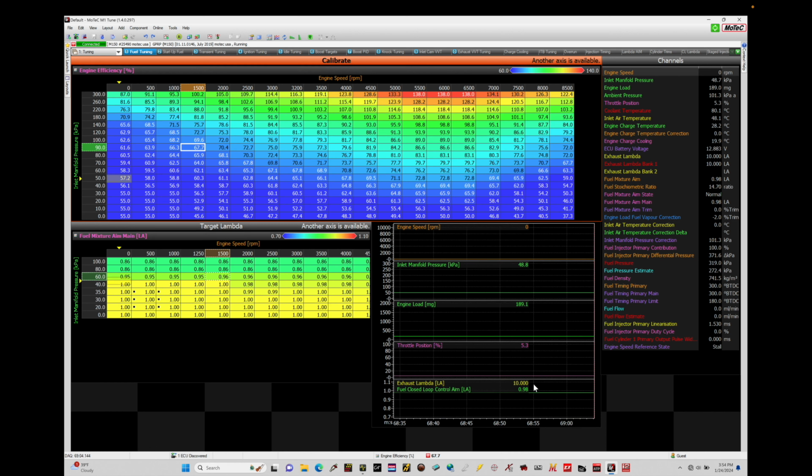So we utilize this within our calibrating and tuning process, dialing in our VE table, for example. We also use this when we're not hooked up to the Motec and we're running it in through different seasonal changes. Let's say we're going from winter into spring, where we have a decent temperature swing. We may find that we have something not modeled exactly right within our air charge or the density aspect of our airflow model, and we may not have our fueling quite right. It might be off a few percent. Well, the closed loop correction will allow us to correct for that. It'll take up those little bit of deviations or differences day to day or in seasonal changes and allow you to have an engine that's always running at that desired target lambda.